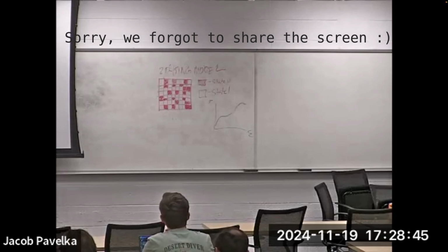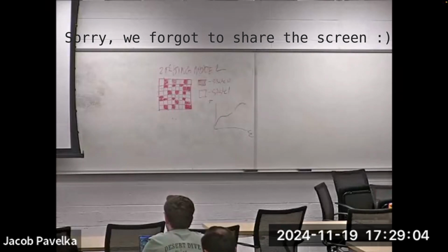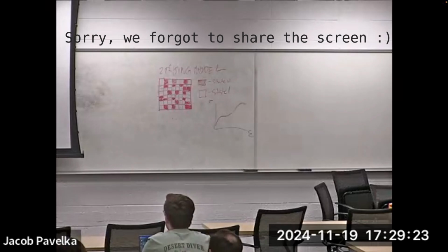I'm going to put Chaitali on the spot because I tried running the canned example in the continuum plasticity codes. This is a simple tension problem. Why is it looking like that? I don't know why it looks like that, but we'll go with it. This mesh has some elastic and plastic constants imbued to the material properties, and we're pulling like this. I was quite surprised to see this result. The stress is quite heterogeneous.